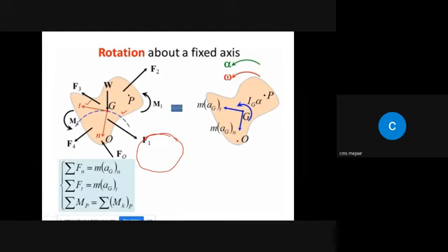So let this axis be called T, and definitely N will be perpendicular to T. How can we draw that T? T is definitely tangent to the path, so anywhere tangent to the path, you can select that T axis. Okay, and N will be perpendicular, and remember N is always directed towards the point about which rotation takes place.